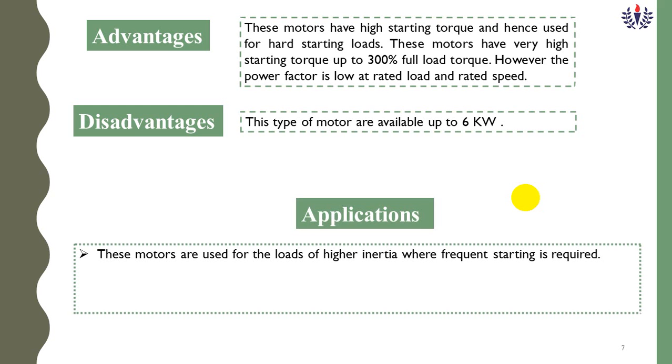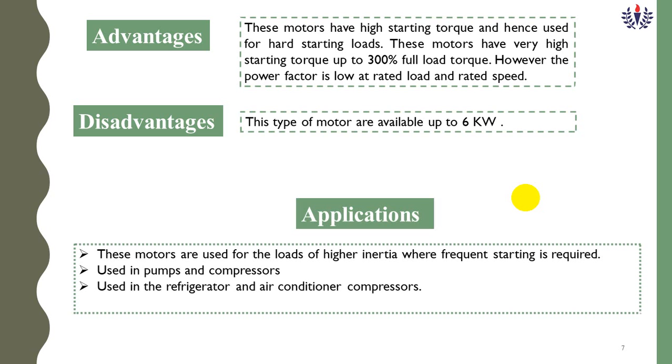Applications. It is mainly applicable for high inertia loads. High inertia means high starting loads. Therefore, where frequent starting is required, it is mainly used in pumps and compressors, refrigerator and air conditioner compressors, conveyors and machine tools. Machine tools means the CNC machines.